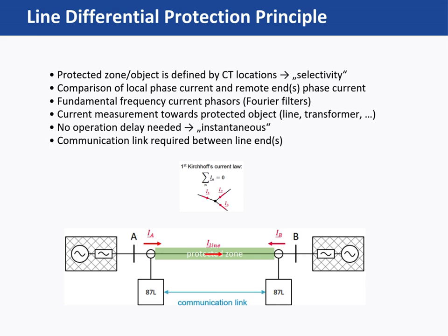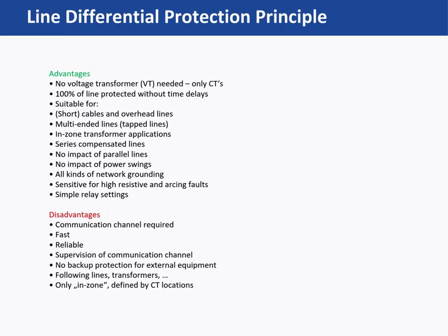Because the comparison is done directly between line ends, no intentional time delay is required, making line differential protection essentially instantaneous. However, this principle does require a reliable communication link between the line terminals.